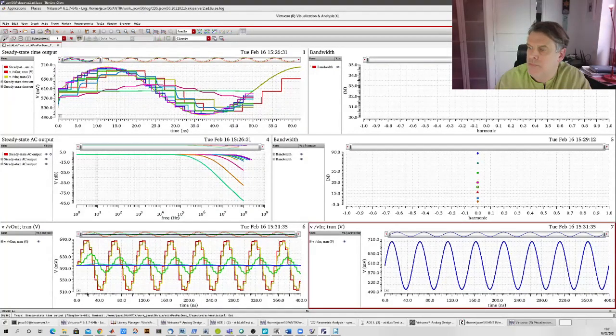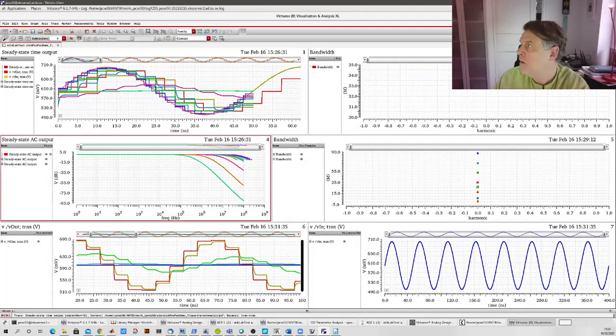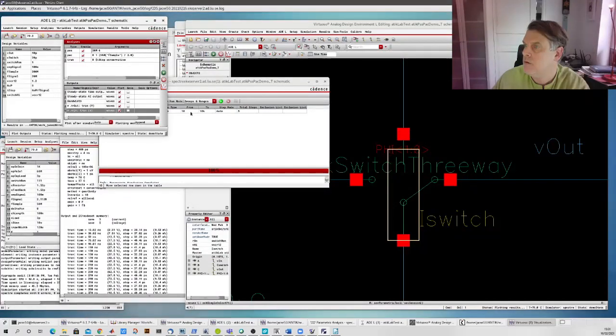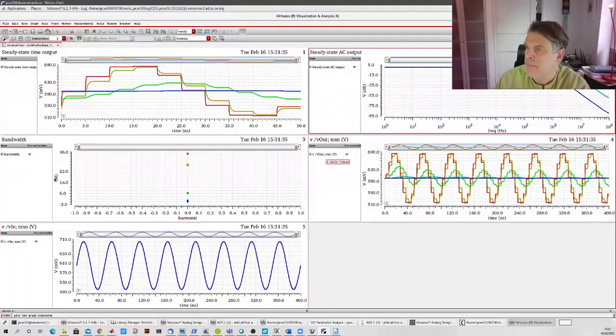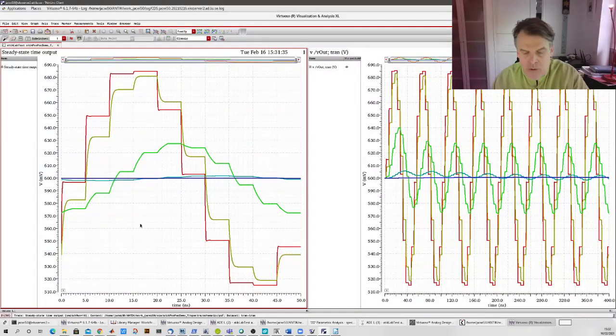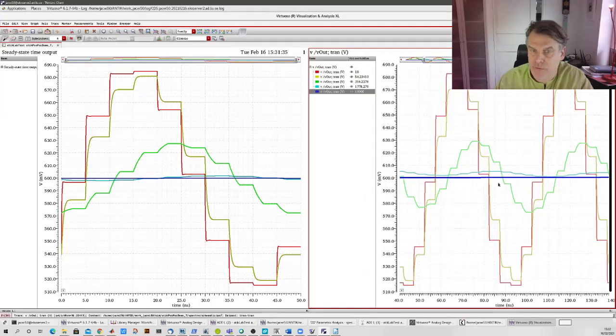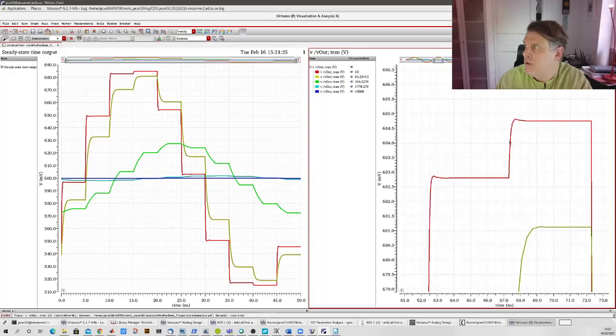And yeah, so let's zoom in on something. I'll just be removing some of the curves, so you get a better zoom in the picture. All right, so there maybe. So first of all, the transient shows here for different resistances. The blue one, almost a straight line, is for a really high resistance system, and obviously doesn't work. For 10 ohms, okay, seems to be pretty good. We can zoom in on the settling here, looks fine, reaches the end value, etc.